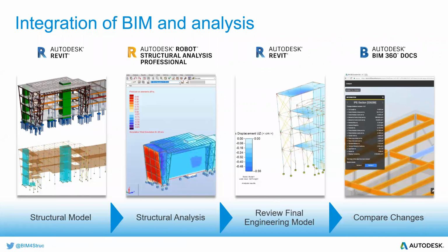And again, it's automatically interoperable, where whatever I worked on within Revit in terms of my physical and analytical model, it's just a matter of a click of a tab, and then my analytical and physical model will be sent to the structural analysis platform within Robot Structural Analysis Professional, and then more detailed parameters can be defined in terms of the local code conditions that you want to use, in terms of the site conditions.